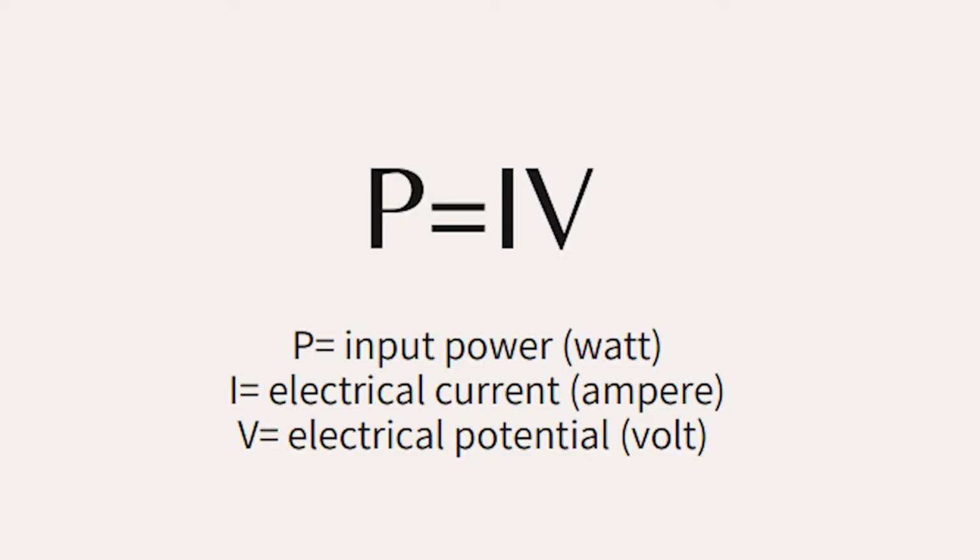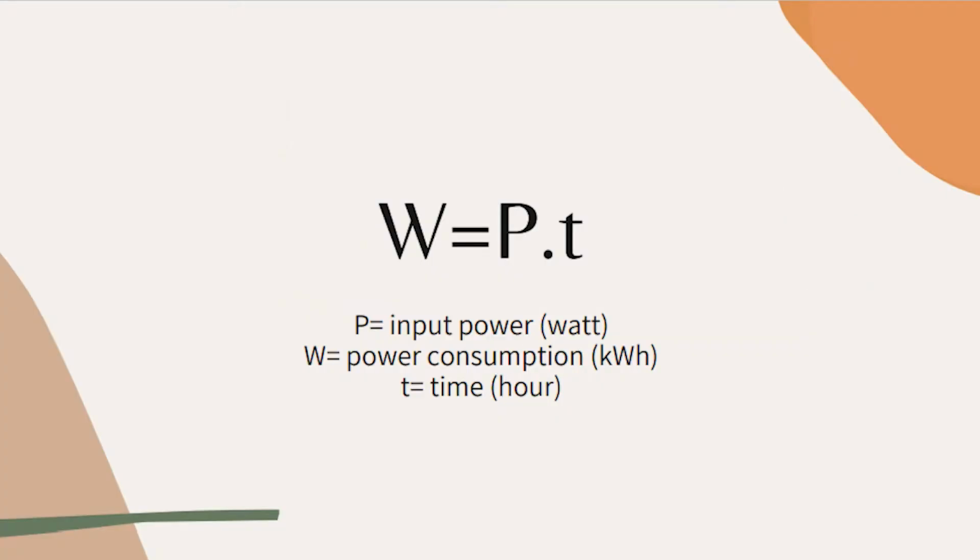I will give an explanation related to the calculation on the selected article. Pressure, air velocity, electric current and voltage are measured from the test conducted. There are 2 different cases in this experiment, with and without condensate water. The input power is calculated by using the formula P = IV, where I stands for electric current and V for electrical potential. Power consumption is evaluated by multiplying the calculated power by time.